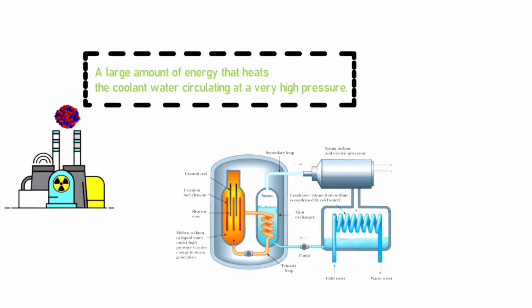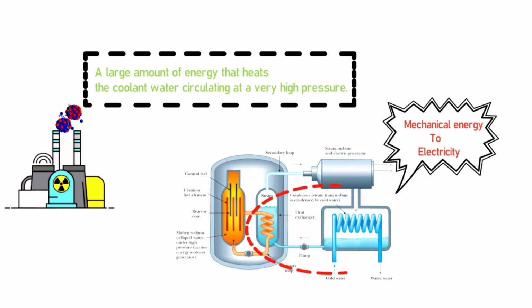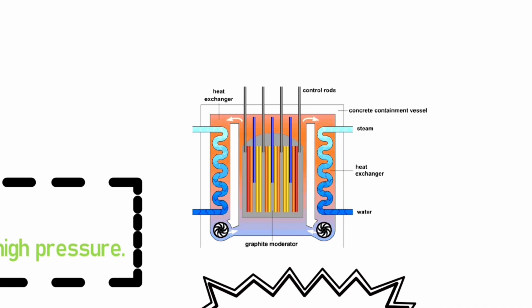This steam is transported to the generator turbine set via a secondary circuit. Once there, the vanes in the turbine move the alternator and the mechanical energy is transformed into electricity. When the water steam goes through the turbine, it is sent to a condenser to cool off and become liquid water again. The water is then transported to the steam generator to become steam again inside a closed circuit.